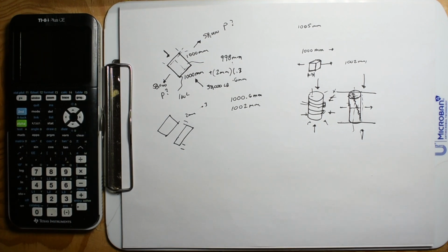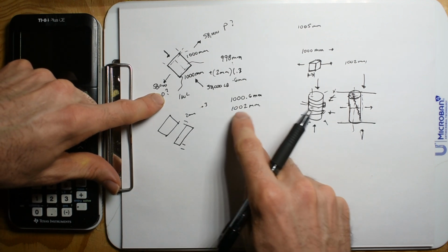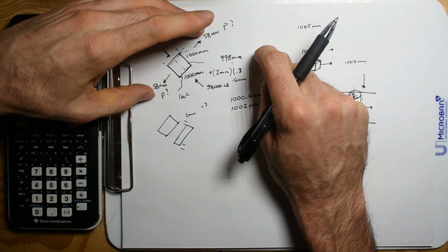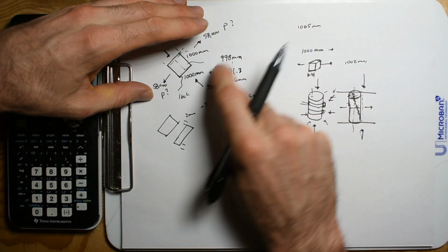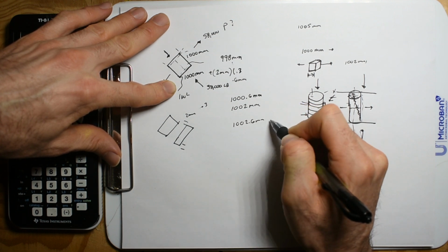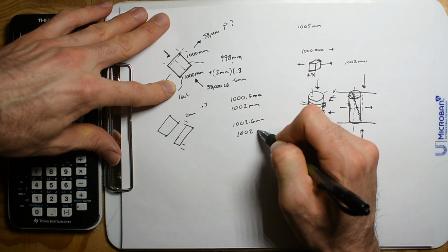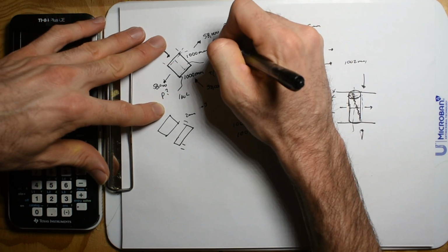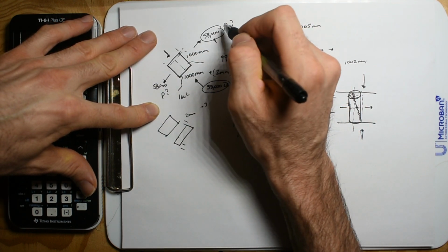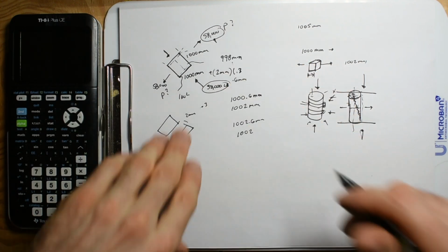So if we applied this 58,000 pounds, we would move it more, another 2 millimeters. And so then the thing would be 1,002.6 millimeters, and we're over. We're 0.6 millimeters too much. So we can't actually apply this 58,000. So the question is, if this is going to be equal to that, what's the max load that we can apply?